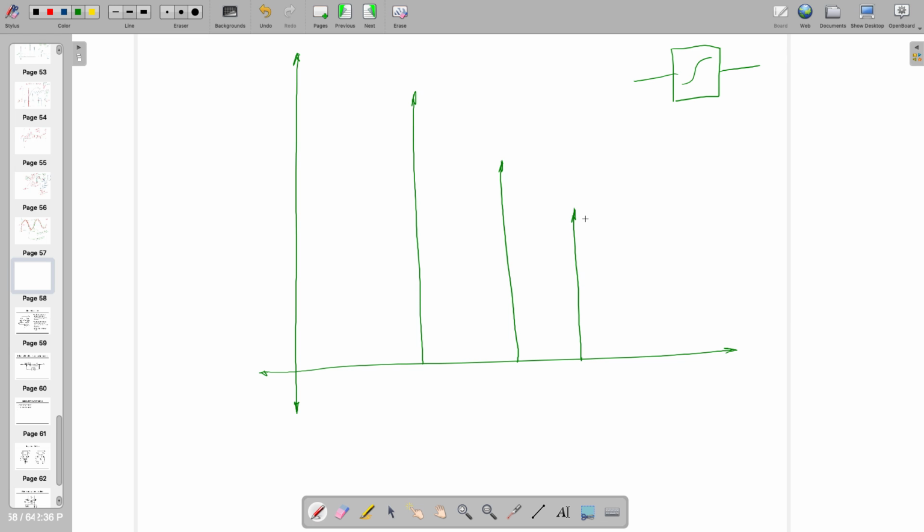First of all, my suggestion is whenever you are dealing with any non-linear circuit, and if you are interested in something called SNR, THD, or anything harmonic related, you need to check whether your sine wave is leaky or not. First of all, you are going to see the FFT of the sine wave, where you are going to see only one impulse at the input frequency.